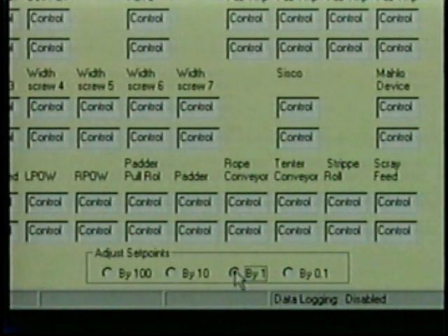If you want to make a device go up by 1 as in the speed of the pattern, set the small black dot on Adjust Set Point value of 1, then move the arrow to the top box of the pattern, and you would left click 1 time, and that will make the speed go up by 1. If you want the pattern to go down in speed, you would simply move the arrow to the lower pattern box and click the mouse left button 1 time, and that will reduce the pattern speed by 1. All changes on all device set points work the same way.